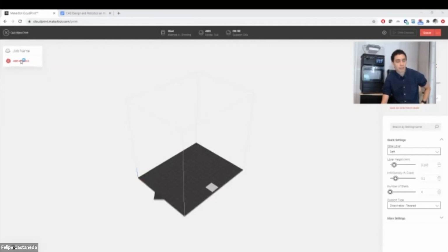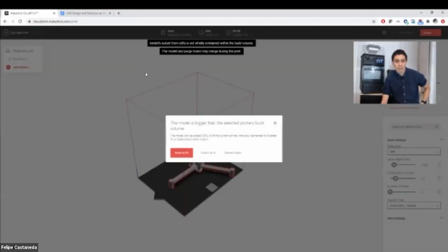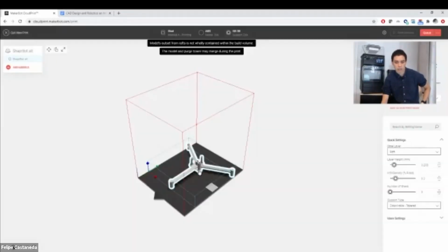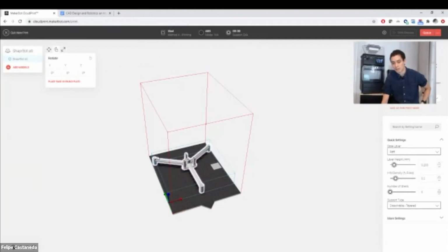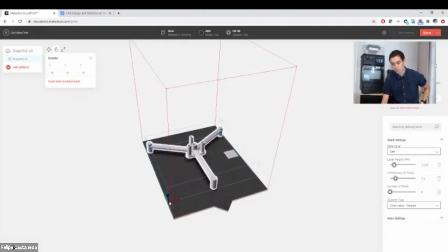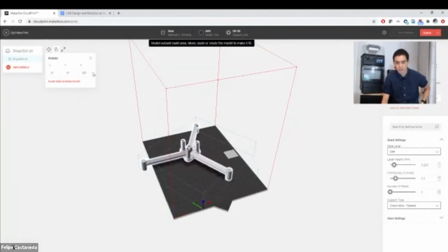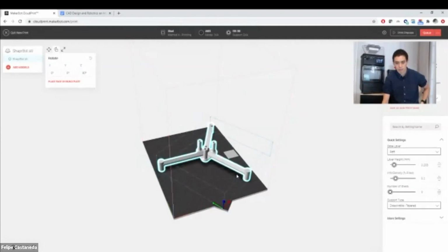And while I do so, the origin itself, especially after the file has been exported, is fairly straightforward to change here. As you can see, the origin access point is now reset, and it's unique to the part itself. It's taking the bounding box of the part and putting the origin point of this body in one of the corners of the bounding box. In this case, I'll just rotate my part a little bit so that it can fit nicely in my build plate. There we go.